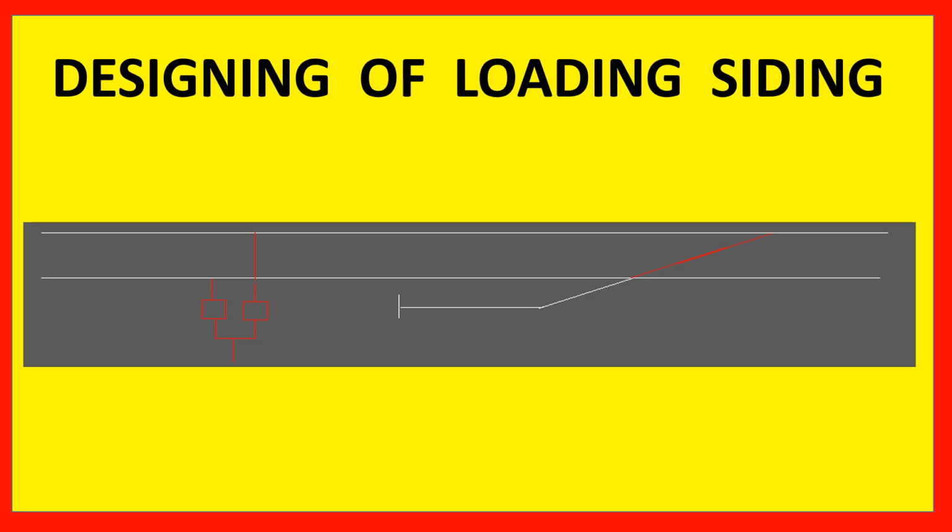If you take only from up line, then during power block on upline, the siding will not get any power. You have to confirm the reliability of power supply. So you are taking up and down, or the two up and down last line, if multiple lines are there, so that it will not be under shutdown immediately.